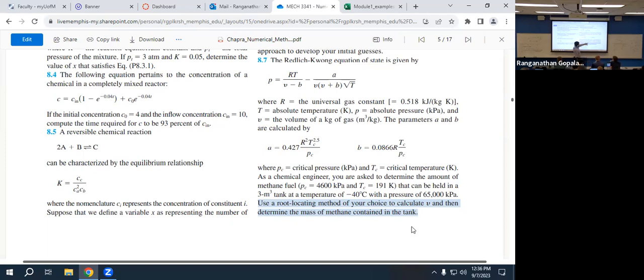The temperature has to be in Kelvin. That's a major thing. Otherwise, this equation will not work. So if you put everything in, you have pressure being a known, equals RT, temperature also being known, specific volume minus B minus A times V plus B square root of T.